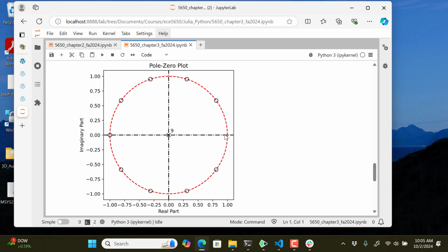And in the case of the rectangular window, the number of zeros in the denominator, remember, was z to the m minus 1. So if m is 10, we have 9 poles at z equal to 0. That's what that represents right there. And then here's all of the zeros spread around on the unit circle. And there was a pole and a zero sitting over here, but remember, they were canceled out in the math. They were annihilated.